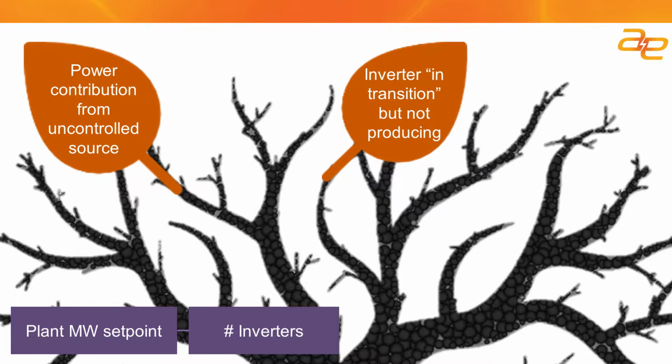It might also be the case that if there are workers working on the line, the inverter is going to wait for 5 minutes with reliable power before it kicks on. That way, if somebody working on the line closes in a breaker, the inverters aren't just going to jump on, start producing and delivering power.